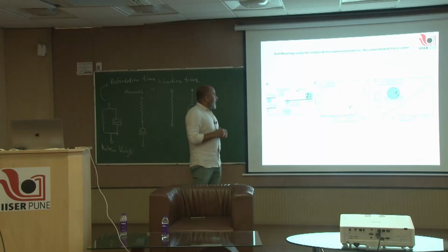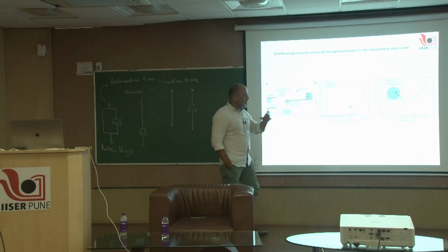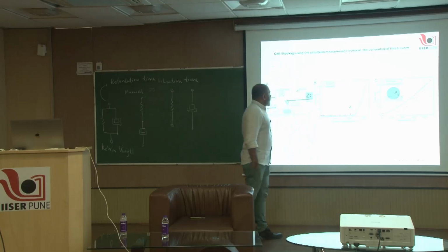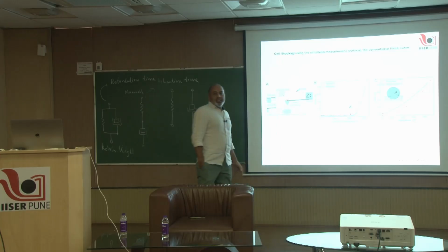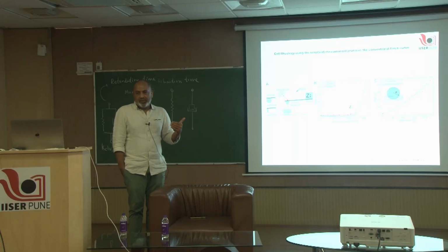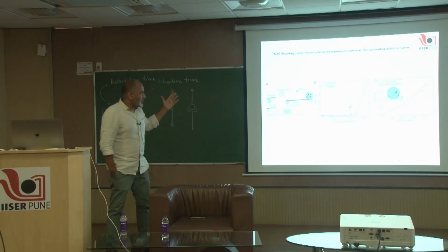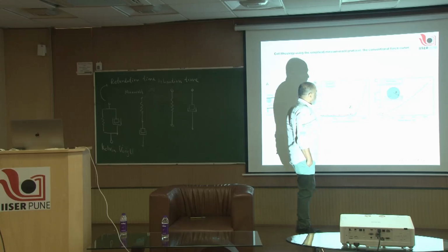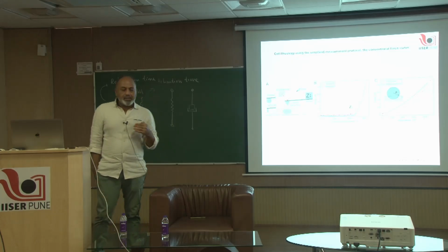And after you have done this, had this been a fully elastic material like a Hookean solid we talked about, it would have been going there and coming back along the same line. Now, the reason there is a hysteresis in this kind of curve means that some part is viscous, some part is not fully recovered and also not assisting you while you come back, and that is why for the same value of strain, you get different stress values, right. That is what the hysteresis means, while you go and come back.